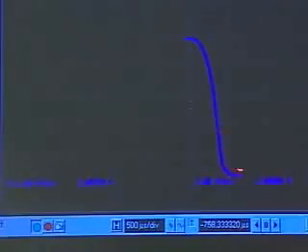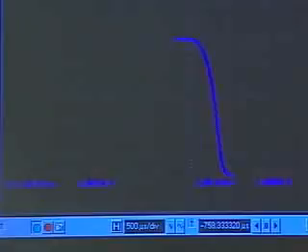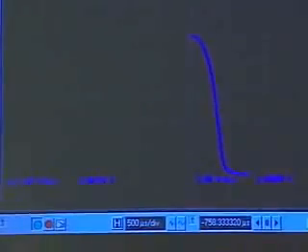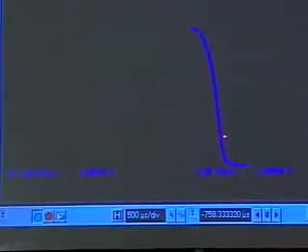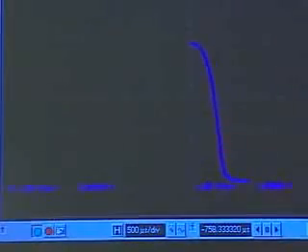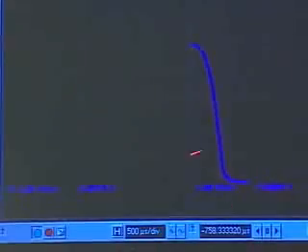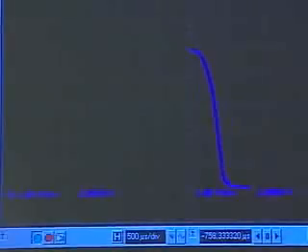This is the triode region of MOSFET operation. So the MOSFET's in saturation, things are going great. As I increase my Vi, at some point I go from the saturation region and transition into the triode region, and this value shown here gives you the corresponding input voltage and the output voltage.